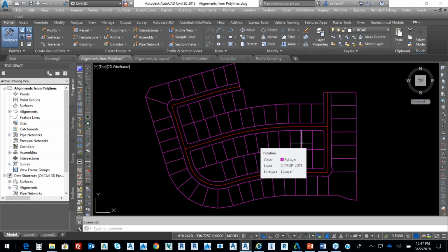So I just want to give a couple different scenarios. One would be create an alignment straight from the polylines that an individual gives you. The other would be reversing that alignment, making sure everything is tangent from the data that they give you. Also, manipulating and modifying the specific objects of that alignment, whether I want to modify the curve, point of tangency, point of intersection. So those are just some of the things. And then one of the things that's critical is the site that we put these things in.